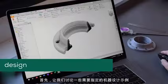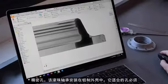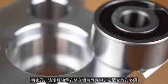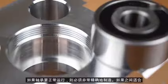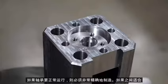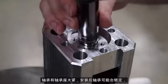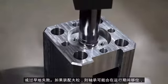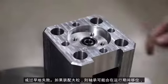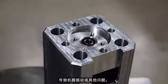First, let's talk about some examples in machine design where you would need to specify a precision bore. This ball bearing is mounted in an aluminum housing. The bore it fits must be very precisely made if the bearing is to function properly. If the fit between the bearing and the housing is too tight, the bearing might lock up once it's installed or fail prematurely. If the fit is too loose, the bearing may shift around during operation, leading to vibration or other problems in the machine.